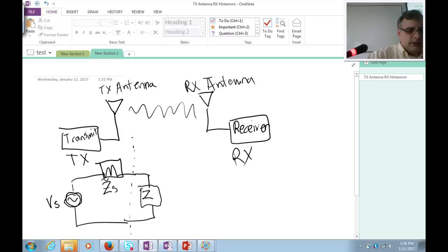When it's used as a transmitter, an antenna behaves as a load with some impedance Z sub A. Notice I put squiggles on top of them because we're talking about phasor quantities. That's how I deal with phasors. Some books do bold, some books do script. It's easier to just put squiggles when you're drawing on the board.